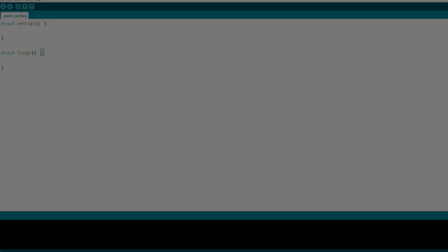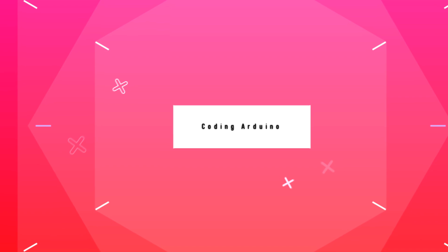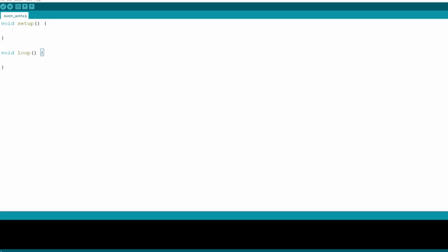Yes, my dear friend, in this lesson we will write our Arduino codes. First, let's include our LCD display library. So let's move to the top and include our LiquidCrystal_I2C.h, and also let's move to a new line and define our LCD screen.